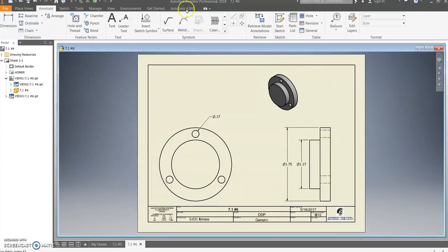All right. So then I have circles here, so I need to make sure that I add center lines to my circles. I'm going to add a big center line here, and I'm going to add a center line to all of these. And I'm also going to add a center line right here. So center line between, actually I'm going to use this one, so that way I can draw it to here, and then left click to place that. And I'm going to put a center line between here and here, and here and here.